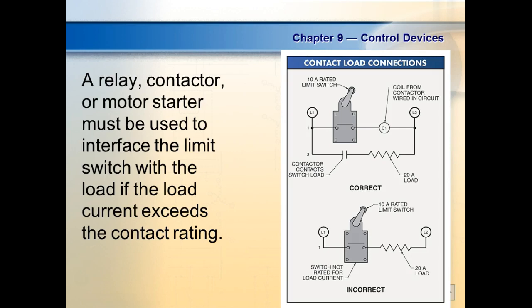Counters, their contacts will stay inside a control circuit. So all these devices that are totally inside the control section of a ladder diagram can be replaced with a program. But we still have to bring inputs in. We can't replace inputs, right? You understand? And we can't replace outputs. Sooner or later, that computer has got to send something to the outside world.